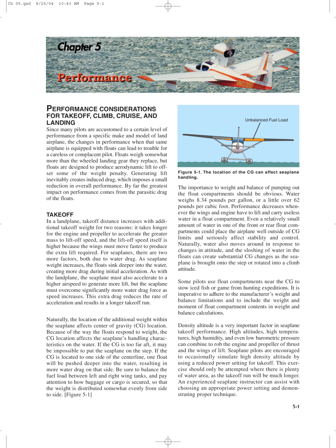Density altitude is a very important factor in seaplane takeoff performance. High altitudes, high temperatures, high humidity, and even low barometric pressure can combine to rob the engine and propeller of thrust and the wings of lift. Seaplane pilots are encouraged to occasionally simulate high-density altitude by using a reduced power setting for takeoff. This exercise should only be attempted where there is plenty of water area, as the takeoff run will be much longer. An experienced seaplane instructor can assist with choosing an appropriate power setting and demonstrating proper technique.